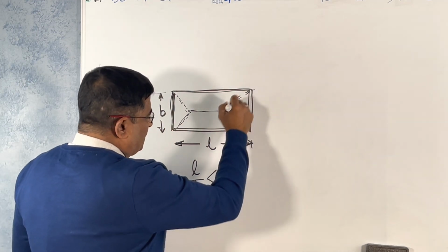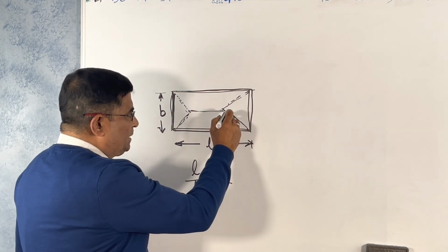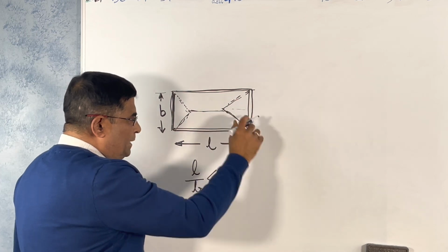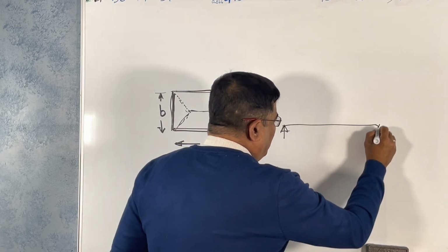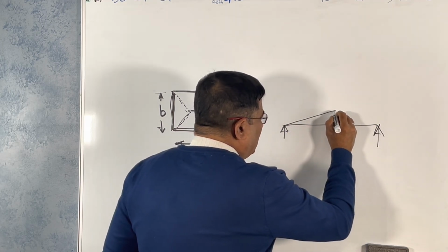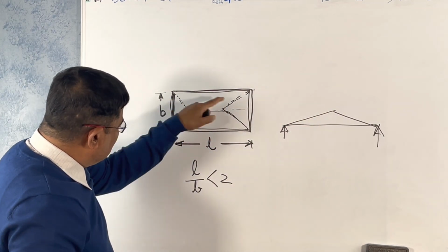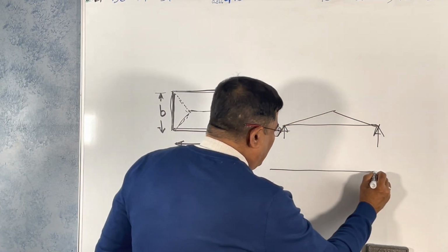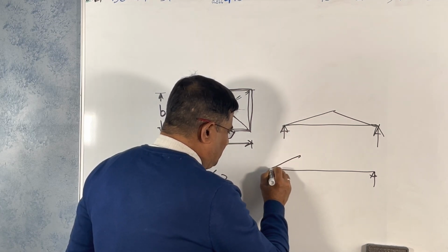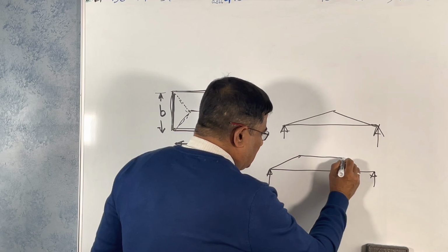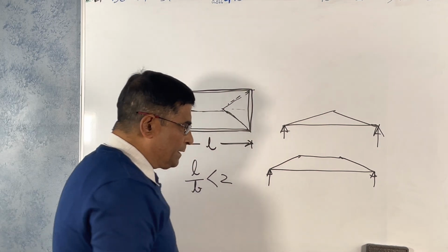So you see this is a triangle, right? This beam will be subject to the triangular load. If you consider this is the maximum intensity, the whole thing will be like this, triangular. The other side, this beam, will have a trapezoidal load. That means part of it is linear, then constant, then again linear: trapezoidal.